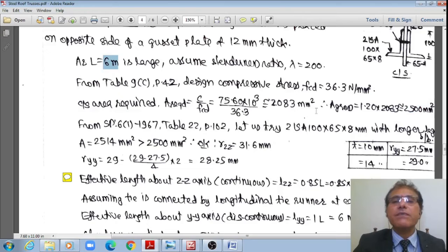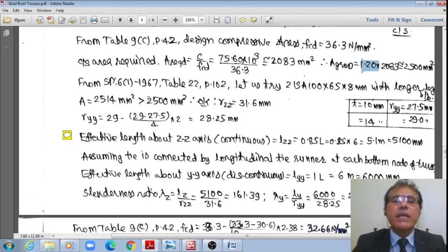Therefore, if the span is large, if the slenderness ratio is more, then you try to increase by 50% more, right? However, I want to optimize the section, therefore I'm just making a first trial with 20% more. If it fails, obviously I'll increase by say 35%. Later on, I'll go with the 50% more, right? That is how I'll go on changing, right?